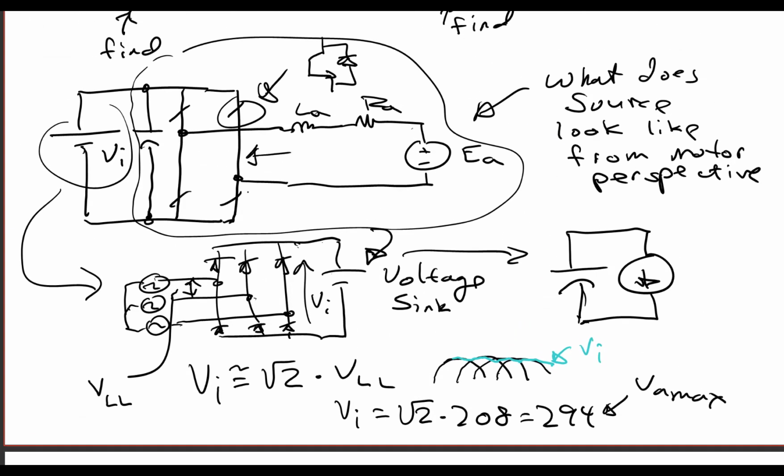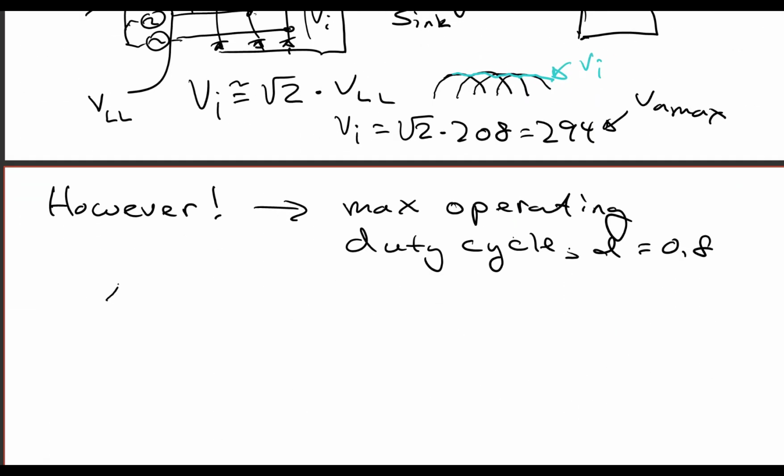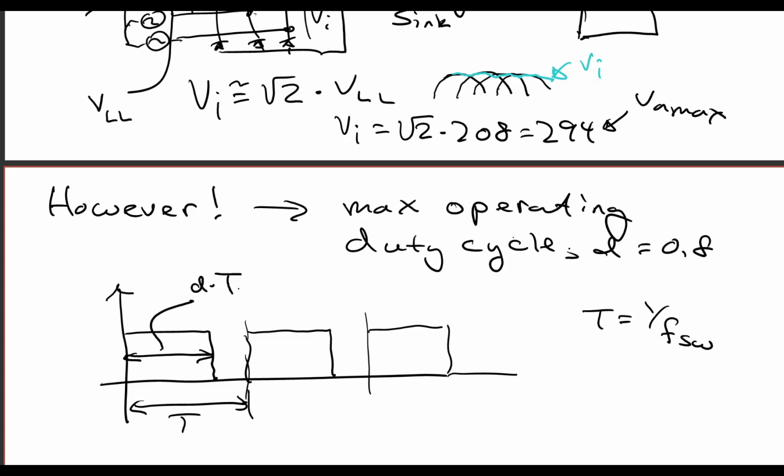This converter here, we're going to talk about this today, is a full bridge converter. It's supplying a voltage that looks like this, repetitive pulsed voltages over a period of T, where T is equal to 1 over a switching frequency, how fast you turn the frequency at which you turn devices on and off. And then this period here is D times T.